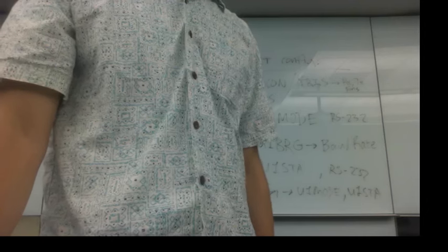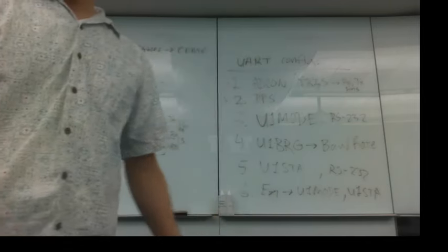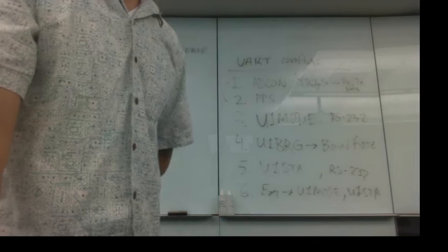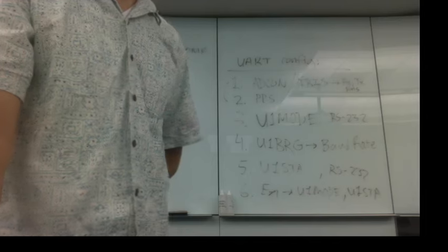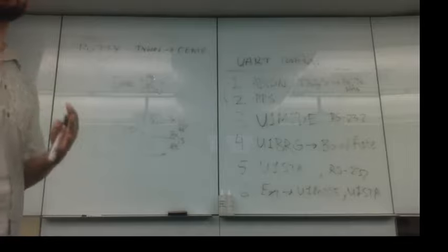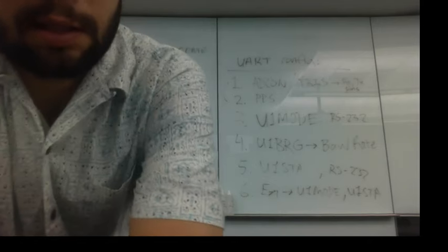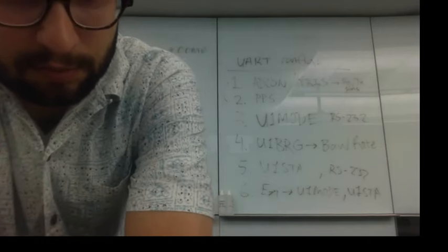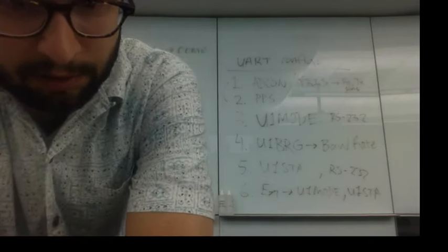So we've got transmit buffer full status bit, transmit enable bit, interrupt mode selection bits for receive and transmit. So the useful bits here are TX enable, I think, is the most useful, because that basically just enables the transmission part of the UART to send things. If you're doing interrupts, you can set the different modes for interrupt status.